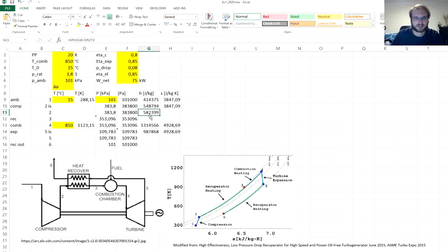And you can see that we get enthalpy higher than the isentropic enthalpy at the point 2. Also, especially for ideal gas, or a perfect gas, the enthalpy is proportional to temperature. So you can see we are also ending up at a higher temperature than if we would go to the same isobar isentropically.